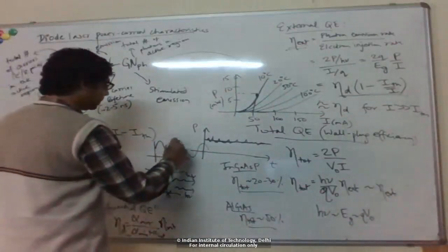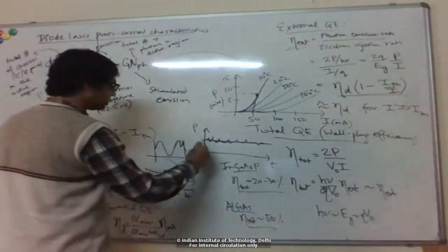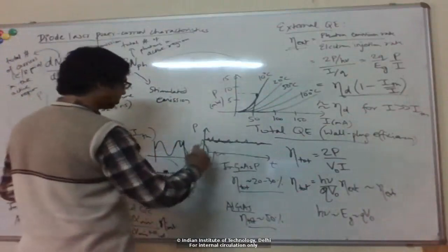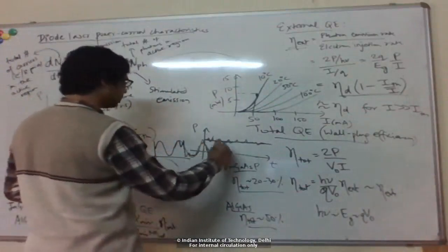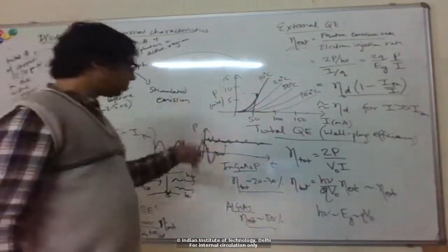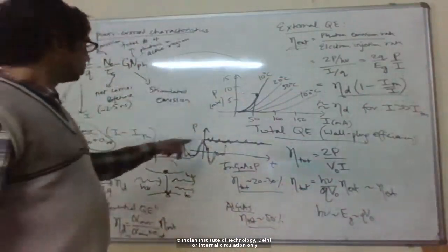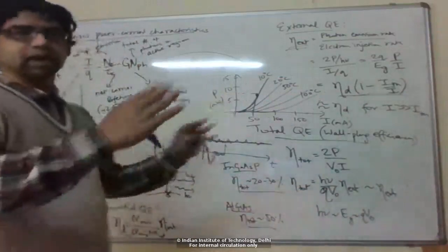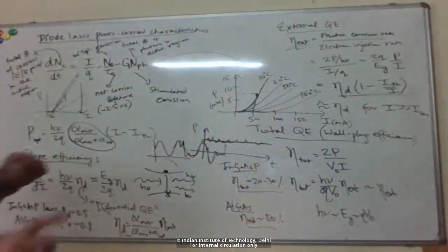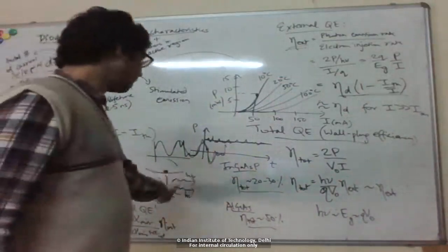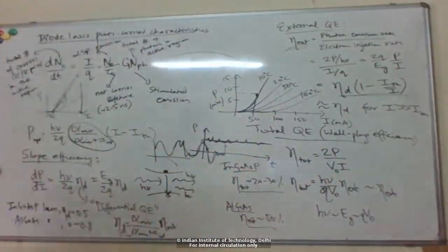But we'll see that there could be some phase jumps happening once in a while, just like intensity fluctuations. There are also phase fluctuations, right? And these intensity and phase fluctuations will give me the line width of the laser. So the more noise here, the broader the line width of the laser. And the ultimate limit will be given by the spontaneous emission.